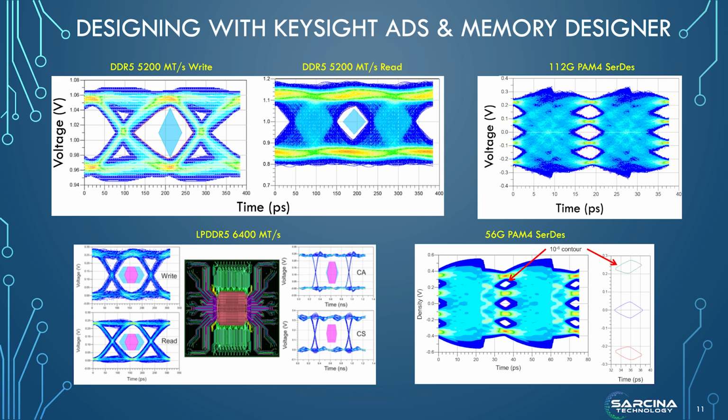This is a very important page. Before you tape out such an advanced, complicated system, how do you know it's going to work? The only way to do that today is to run the system level channel simulation, for both PI and SI. I skipped the PI. Here I show the signal integrity. You can see, for 112G PAM4, for 56G PAM4 DDR, we are all using Keysight ADS and Memory Designer tools to validate the design. Then we tape out.